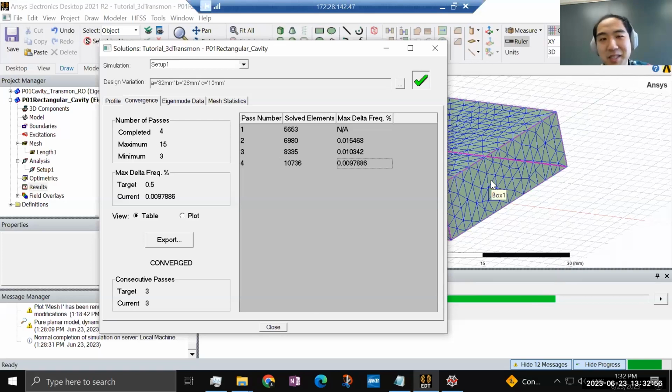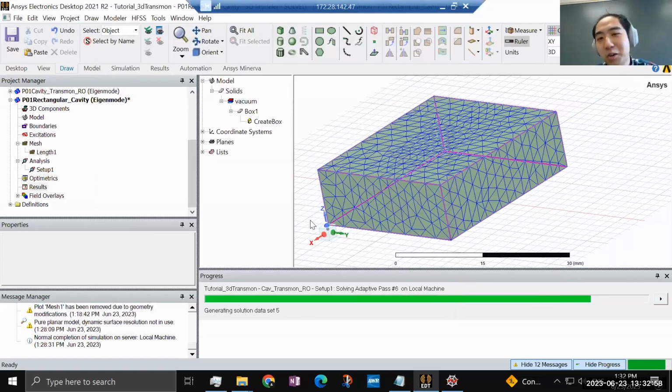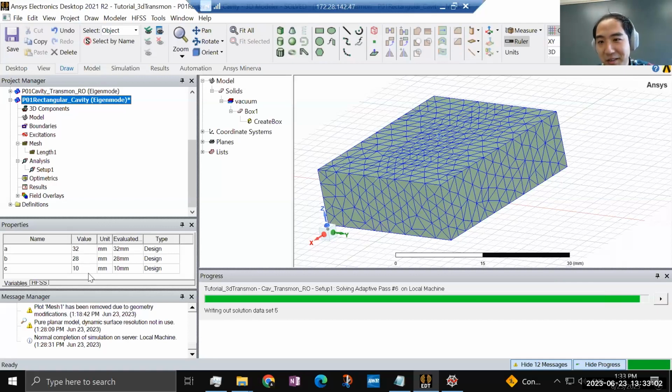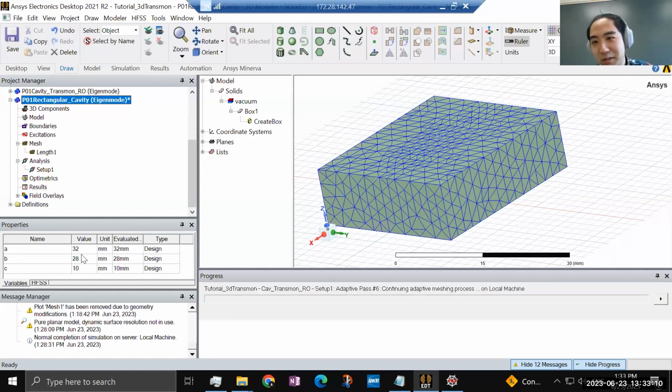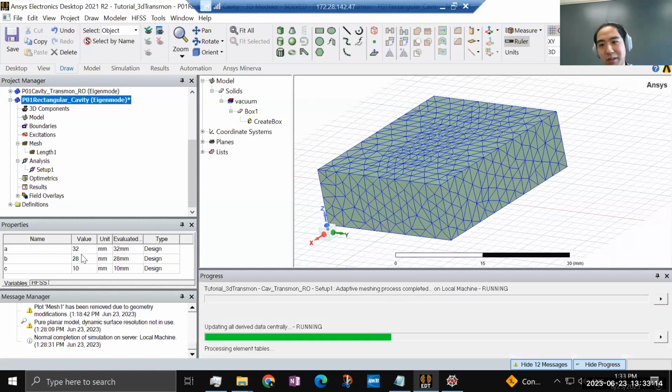In some sense, how good is your control of the parameters? You don't have precise control with higher precision than your caliper, right? And when you cool something down, the dimension of any 3D cavity of any geometry might have thermal shrink. So it's very common to have deviation from the simulated value due to that kind of reason.